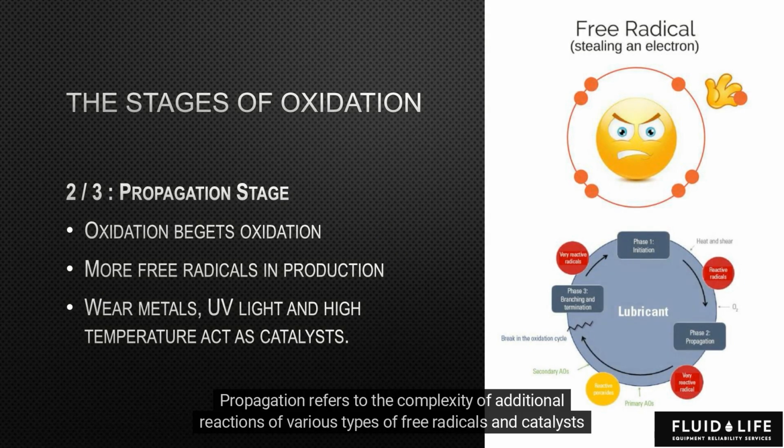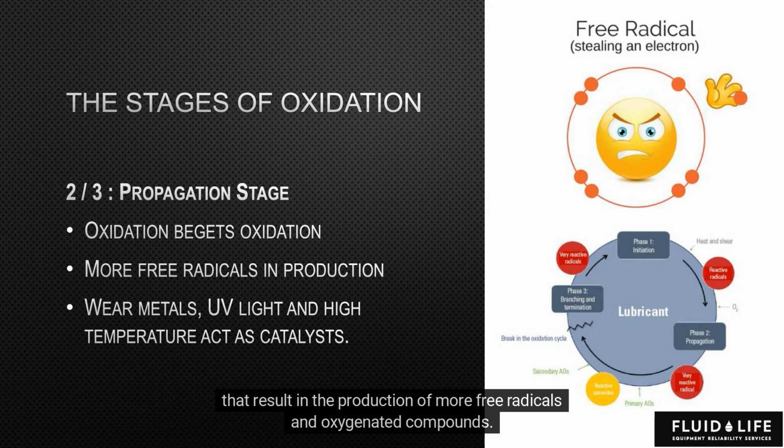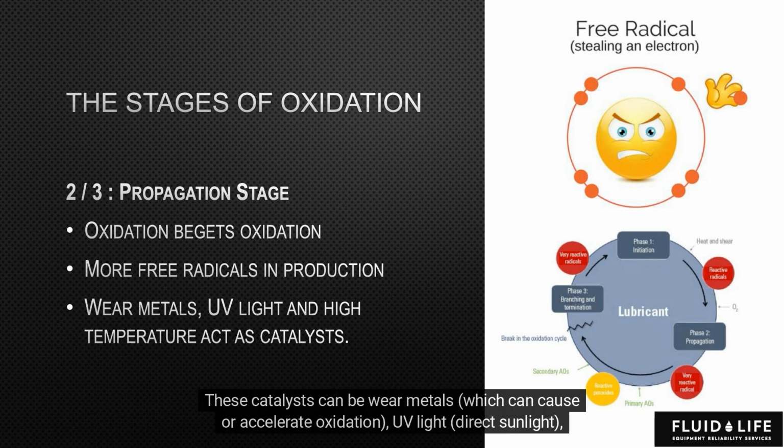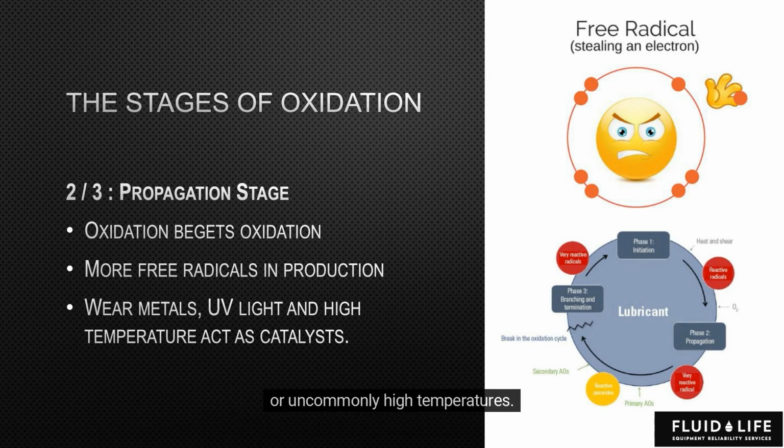Propagation refers to the complexity of additional reactions of various types of free radicals and catalysts that result in the production of more free radicals and oxygenated compounds. These catalysts can be wear metals, which can cause or accelerate oxidation, UV light, direct sunlight, or uncommonly high temperatures.